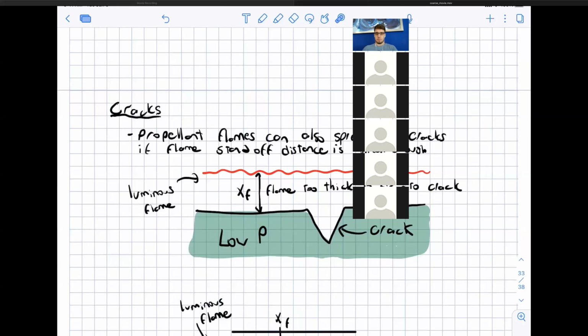Well, the tire is basically a rubbery compound, and the binder of a heterogeneous propellant is a rubbery compound. And if it sits there in storage for decades and ages, the same thing happens. It quote dries out. It doesn't really dry out, but that's just a colloquial way of calling it. It basically self-oxidizes a tiny bit, and it has the appearance of becoming drier. But then cracks will form in the surface.